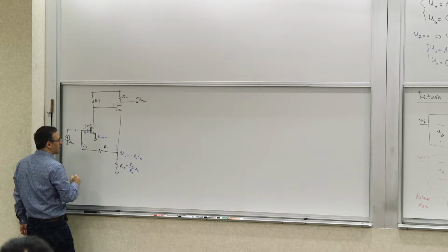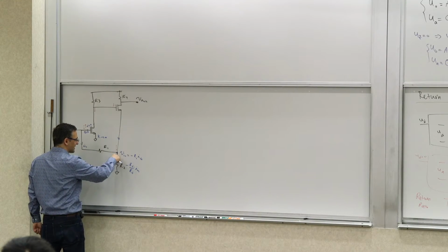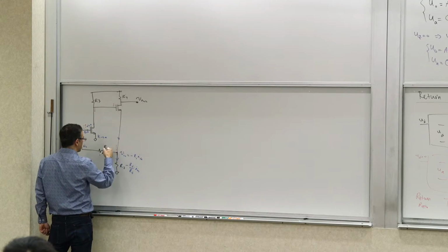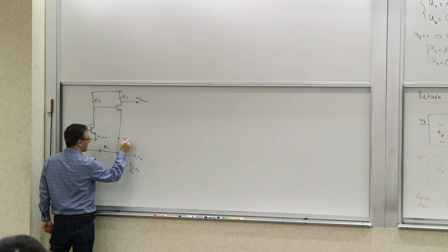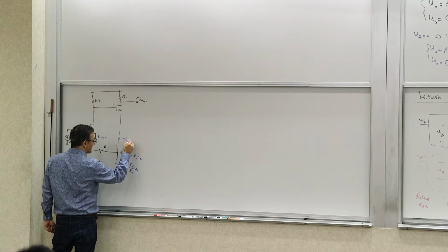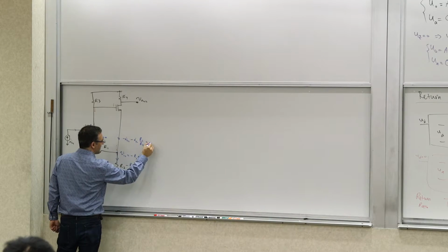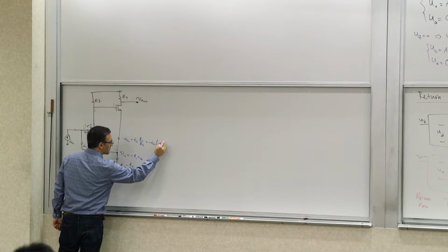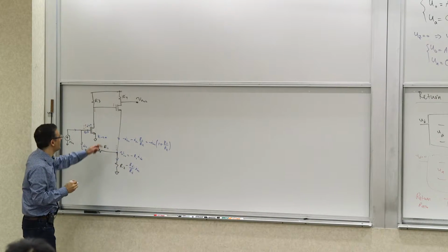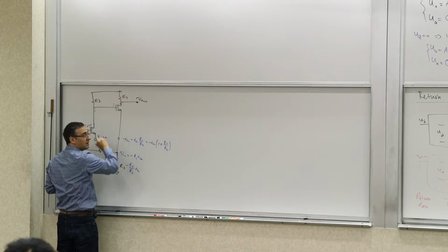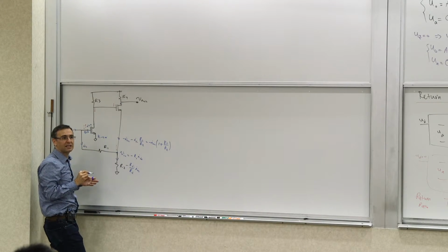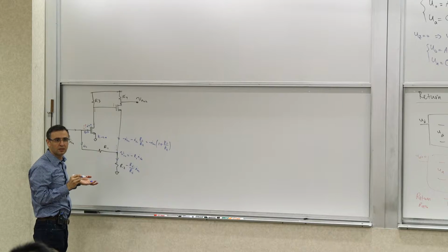right? So this total current is the sum of this current and that current, which is basically negative I in plus this, which is negative I in times R1 over R2. It's negative I in times 1 plus R1 over R2, which is the same current that's pulled out of here, which would be multiplied by negative R4 to generate the output, right?